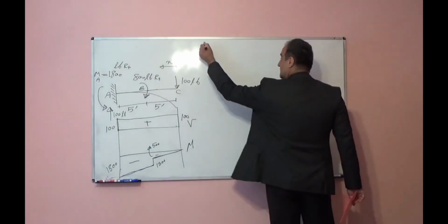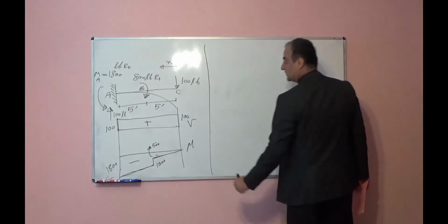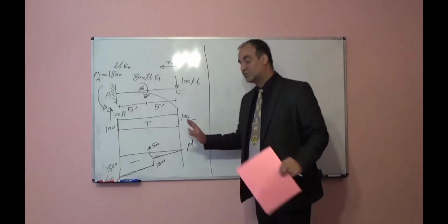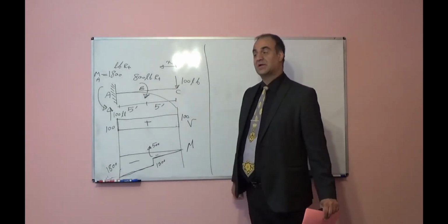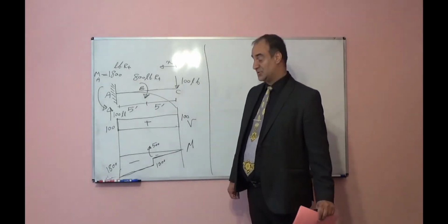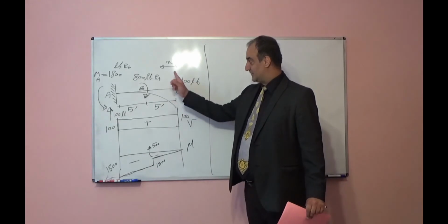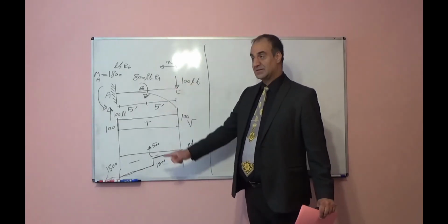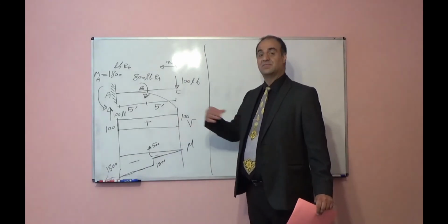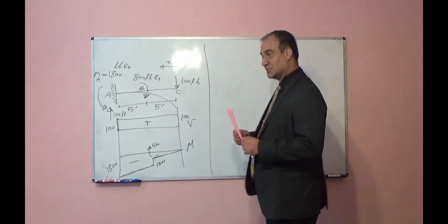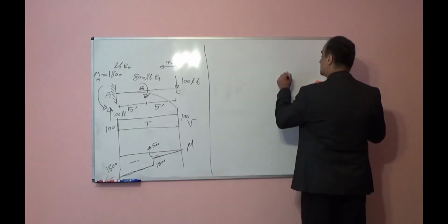Compression force underneath of the beam means negative bending moment. Of course, if you draw like me, it is good, but for the exam you need to show the free body diagram and write equations. You can first draw using the free body diagram and equations, then like me you can double check to see whether your calculation is right or wrong.